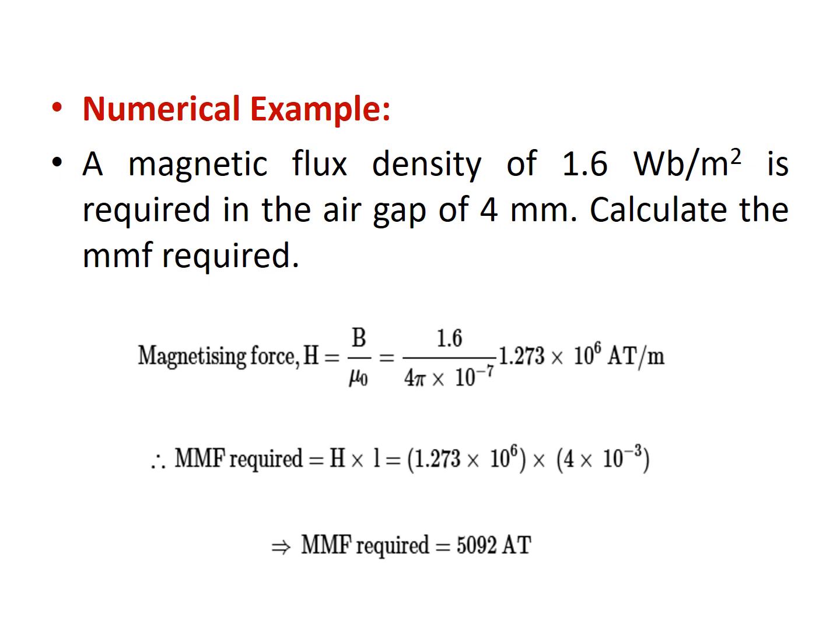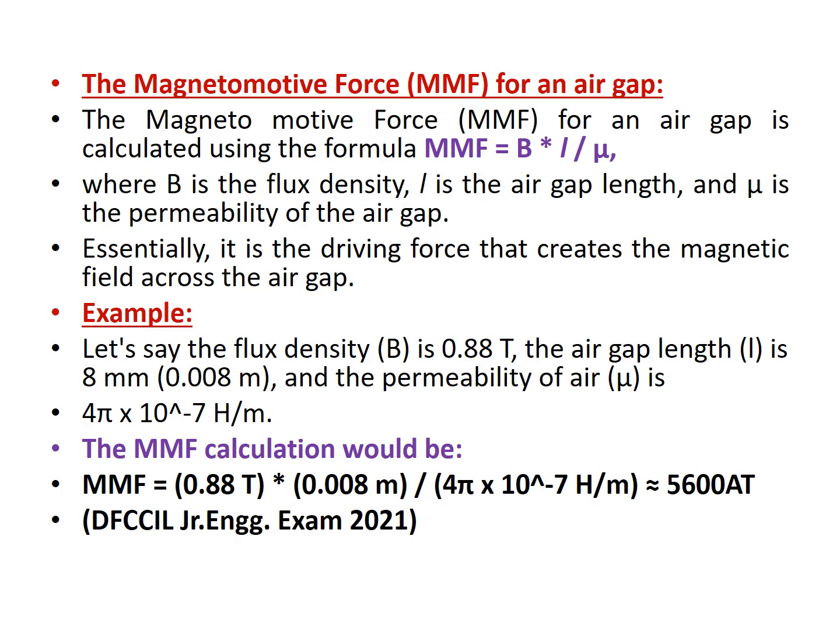Therefore, the MMF required equals H into L, that is 1.273 into 10 raised to 6 multiplied by 4 into 10 raised to minus 3. Therefore, the MMF required for this particular example is 5092 ampere turns.